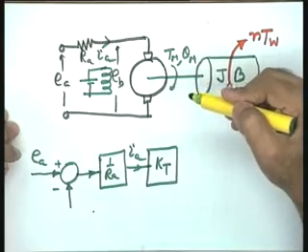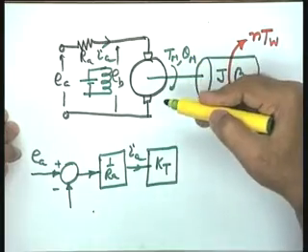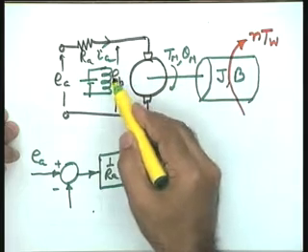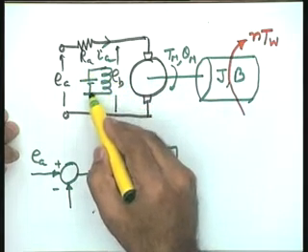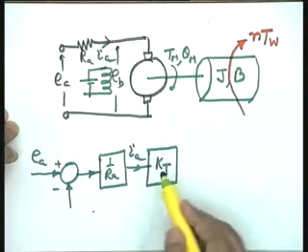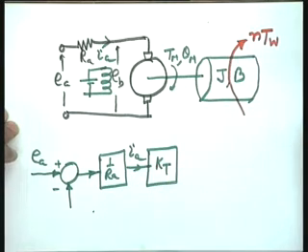You have DC motors, which are permanent magnet motors or wound field motors. So, in the wound field motor, if I give a constant voltage supply, the field is constant, and for the permanent magnet motor, you can naturally take that the torque produced is directly proportional to the armature current. So, the block diagram I am going to give you is valid for both the wound field motor with constant field current or a permanent magnet motor. This point may please be noted.